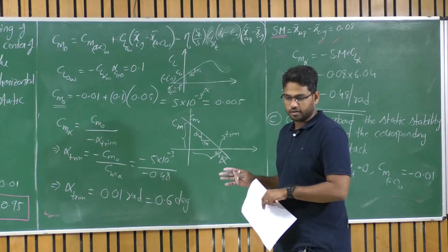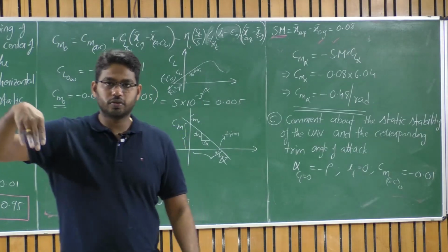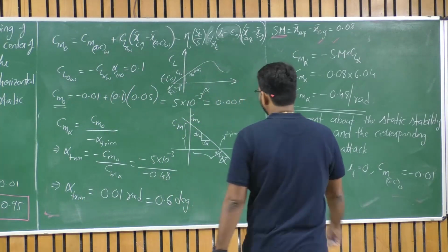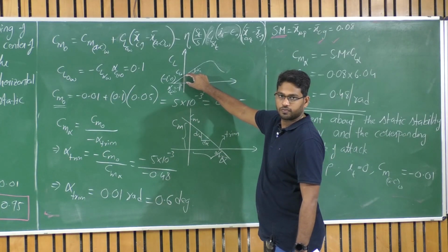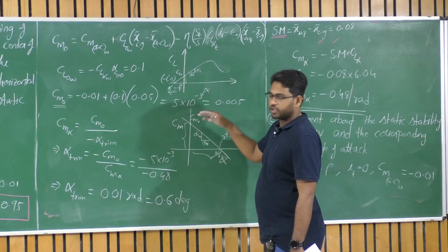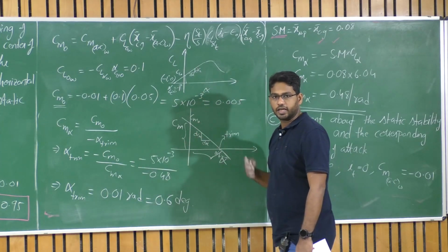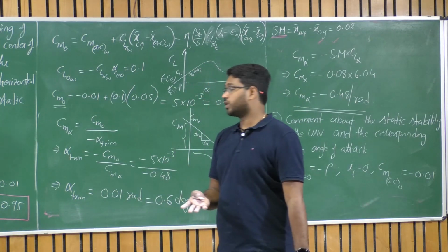Right. So yes, as we discussed earlier, there will be an additional drag due to the trim setting called trim drag. But still we can't afford such low trim angles for this aircraft. If you have to trim at a higher angle of attack, you need to give elevator deflection, which again increases the drag a lot, which is not desirable.